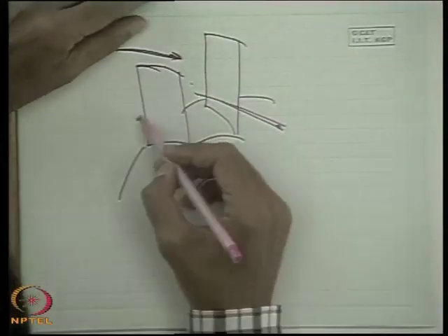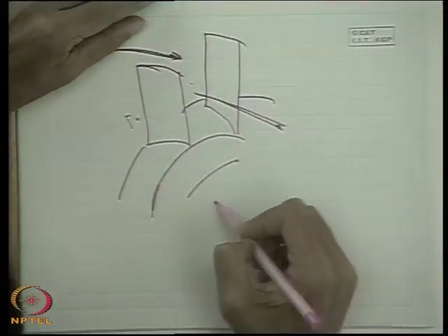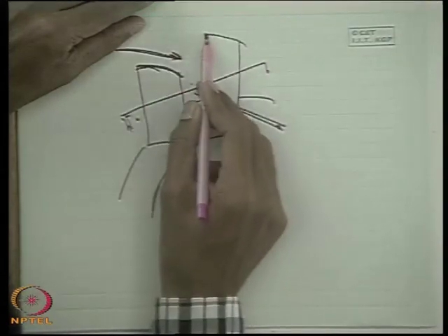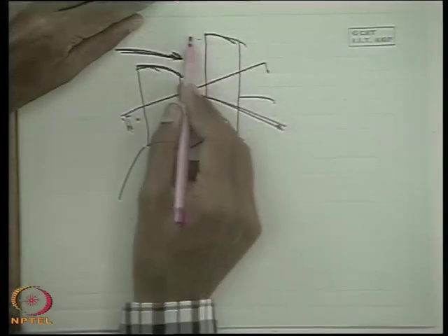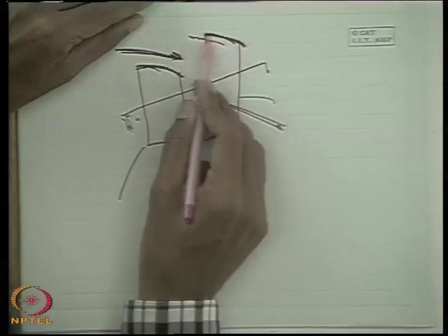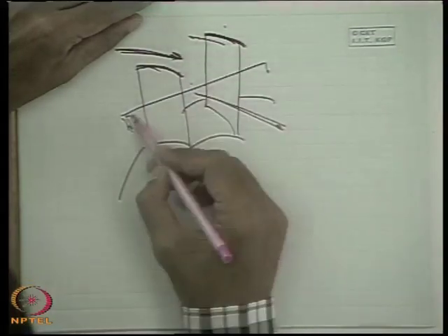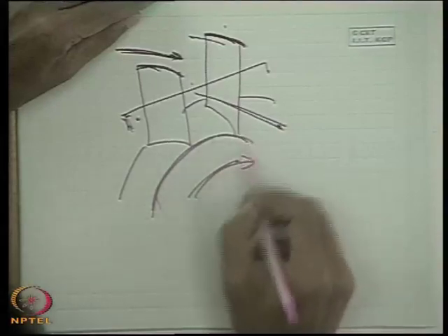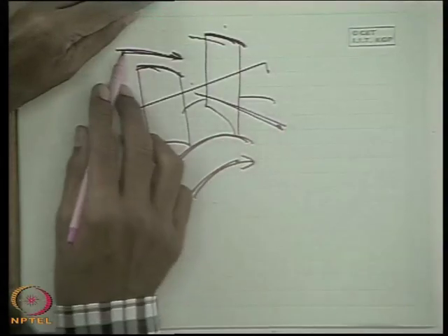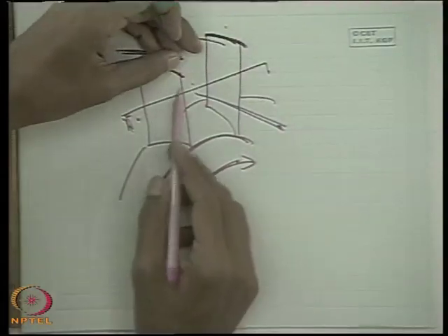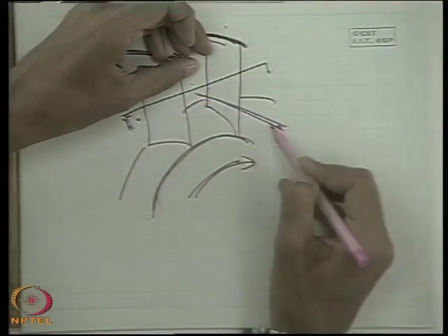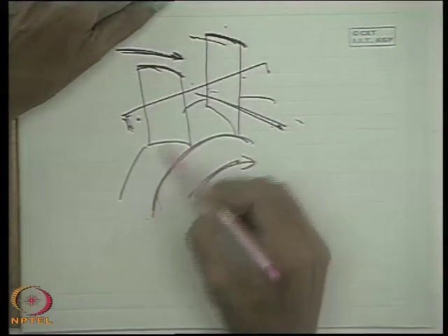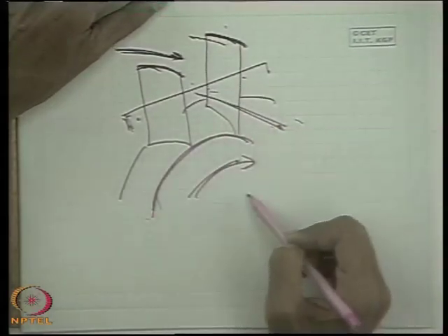If we take a section at the mid section, we will get this curved surface, the flow of fluid through a curved surface. We take any representative section of the blade, see from the top, and this is rotating in this direction, turbo machine. As the fluid enters the blade passages and goes out, this exerts a force and ultimately the turbo machine rotates in this direction.